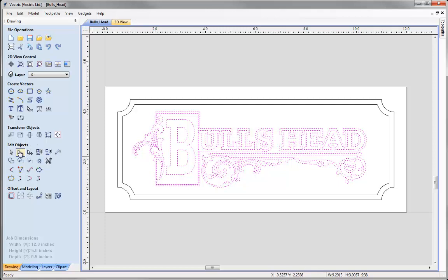To do that, I'm going to click on the icon here so that we can say move, scale, rotate, selection. That is the transform mode, and these handles will appear. Now it's very easy for me to just click there, and if I hold the shift key down, I can just drag this either horizontally or vertically in line. So I may want to drag that horizontally there a little bit further across.